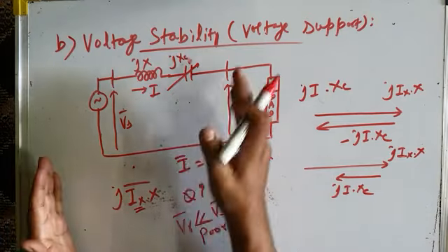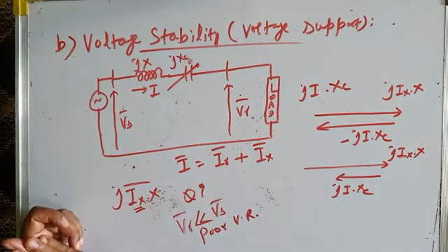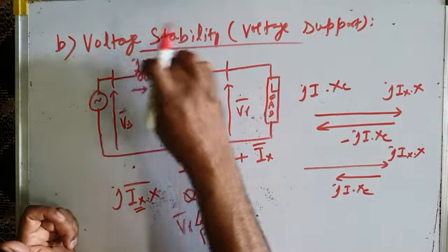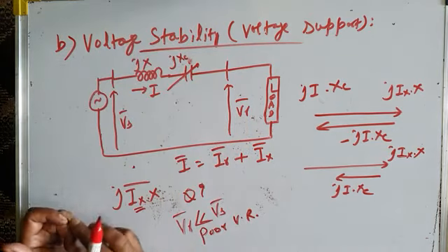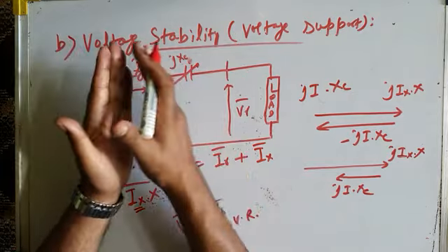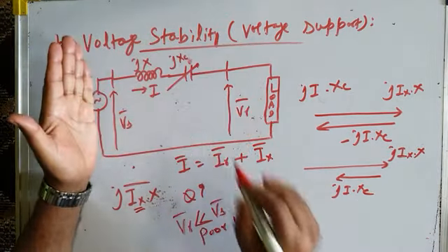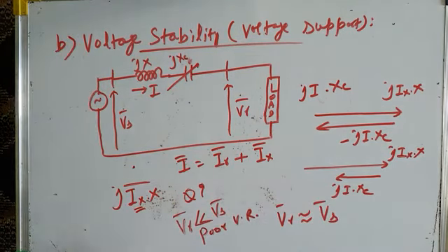Without series compensation, the bus voltage minus this drop may be very large. With series capacitive compensation, this voltage drop nullifies the reactive voltage drop across the transmission line reactance, and effectively it increases the voltage across the line, so that you may make it very nearly equal to Vs, and you will be able to get improved voltage regulation.